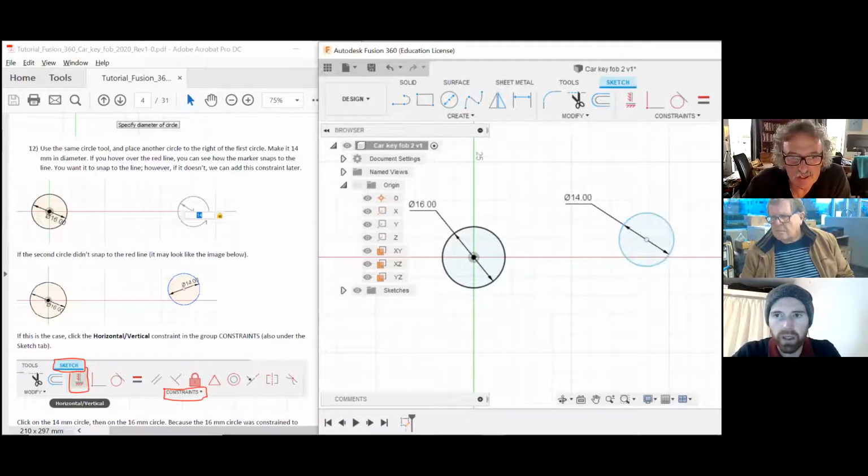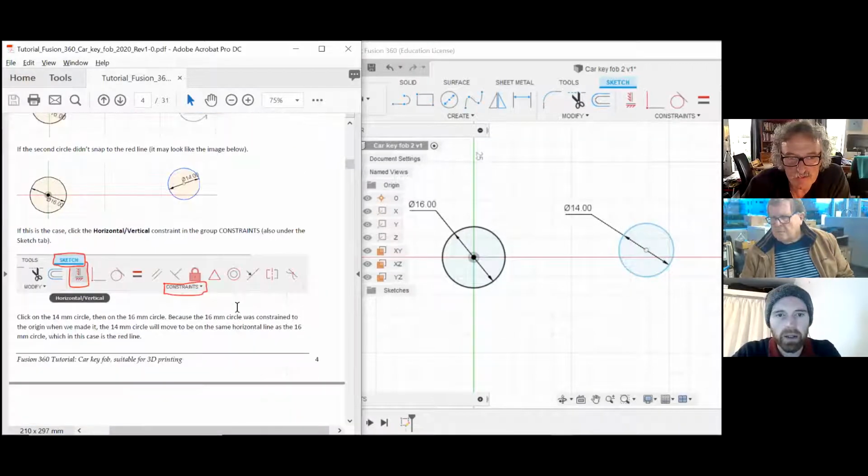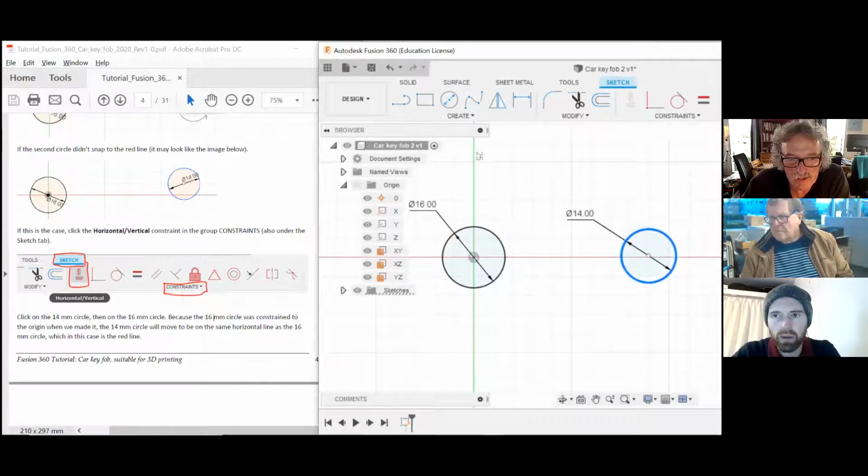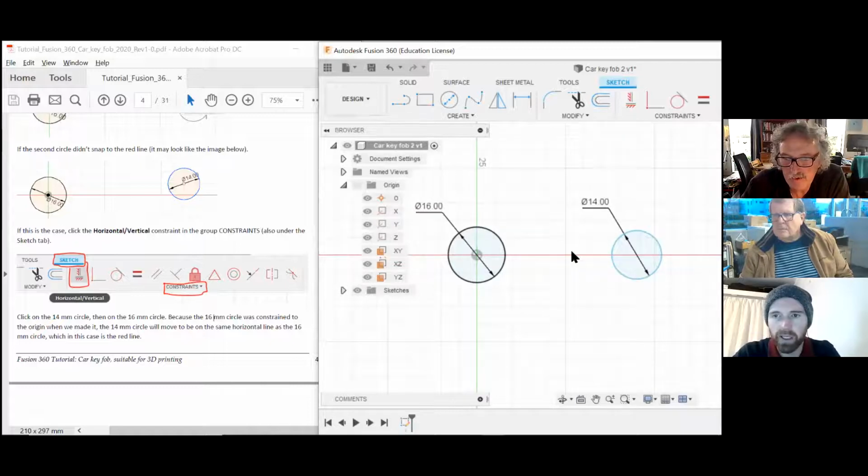How do you drag it? You just click. You just left click and hold. No, that didn't work. You may have to click on the actual circle. Oh yeah. Click on either the circle or the center. Oh, gotcha. I was clicking in between the center and the circle. Oh, okay, and you can move dimensions as well if you want to make your drawing tidy from the beginning.